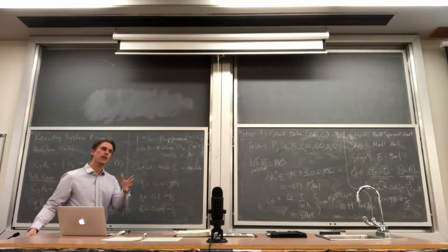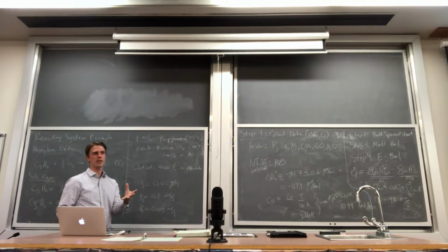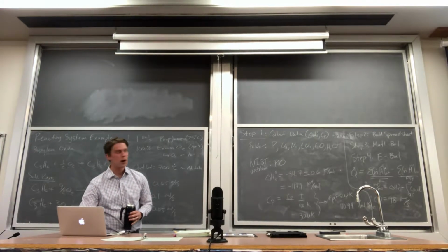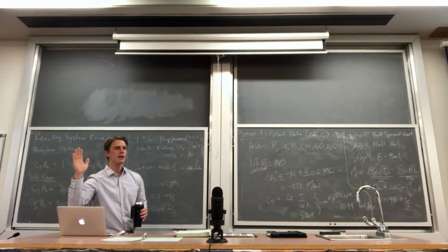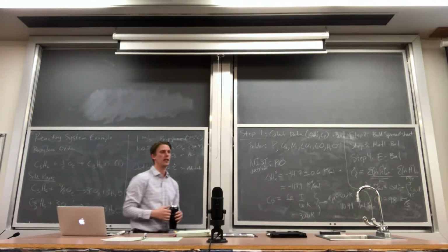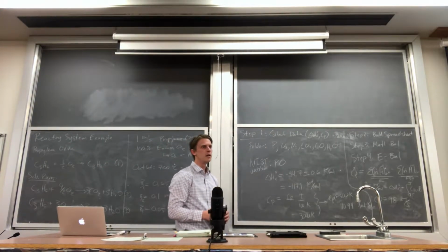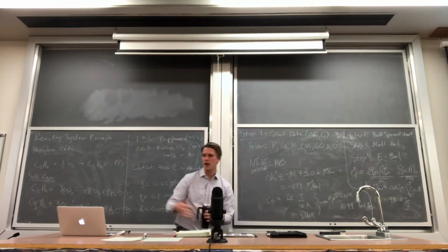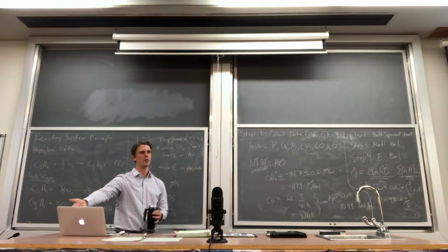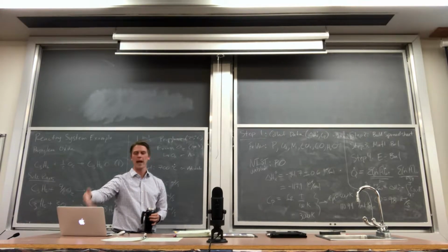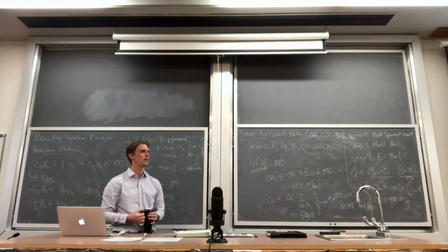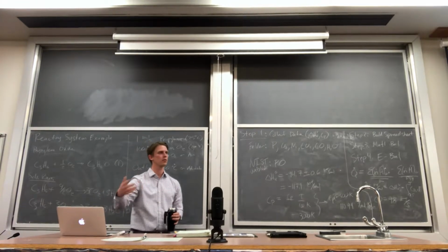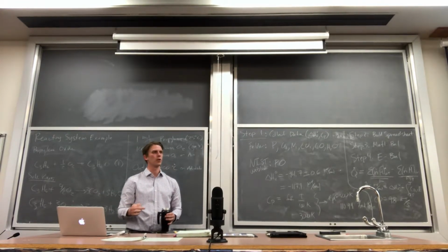And if, let's say, for example, you had a little bit more complex of a process where you had to deal with a phase change, what I'd recommend is I would just shift all of these over to the right, and then I would add in another column for delta H of vaporization. Depending on the problem, you might have to modify this a little bit. But this is obviously for a straightforward all gas phase process, where we have the heat of formation of all the components in the gas phase. But you could see if you modify it a little bit, you could make it more modular for other systems.